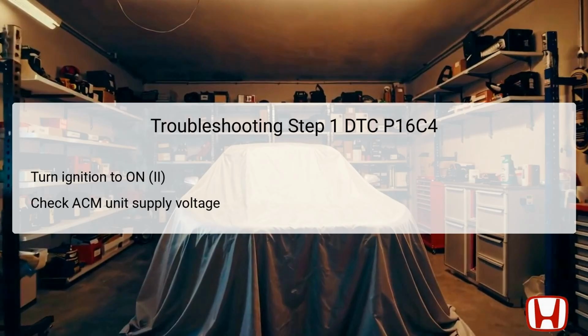If battery voltage is present, it indicates an intermittent failure, suggesting that the system is operational at this moment, but could have underlying issues such as poor connections or loose terminals. Addressing these would require examining the connections at the engine mount control unit and the driver's under-dash fuse relay box. If no voltage is present, further diagnostics will be needed.